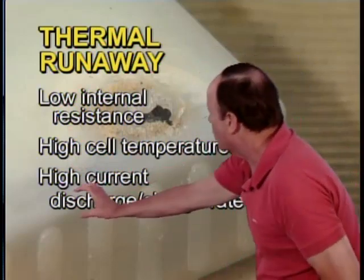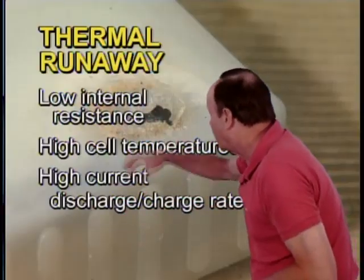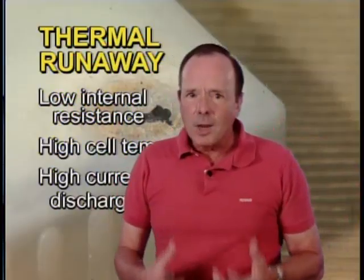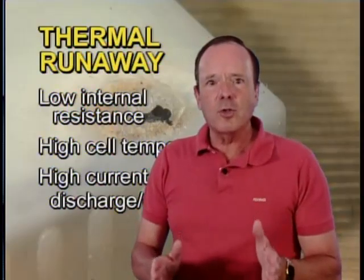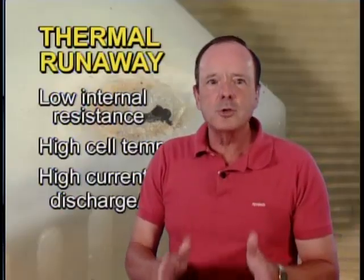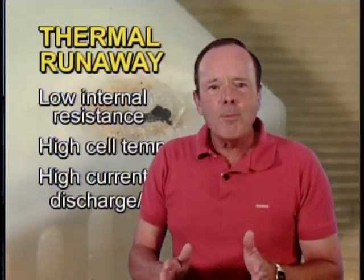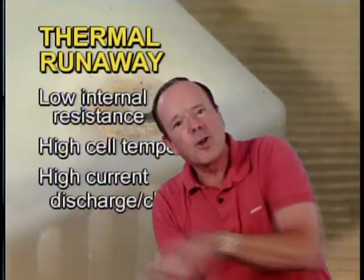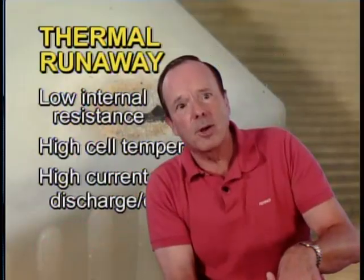First of all, it discharges very quickly, and that tends to heat it up and start this cycle, but it also charges very quickly. One of the reasons it charges very quickly is that we have generators in aircraft that put out a constant voltage. That's called a constant potential charging system. And what that means is when the battery is very discharged, it charges up very rapidly, and that tends to heat the battery even further.